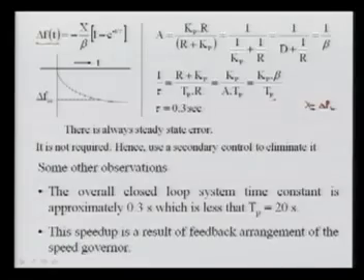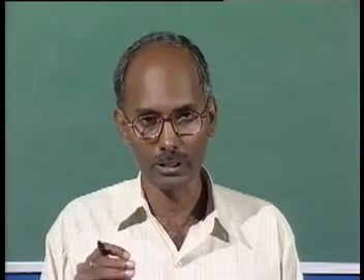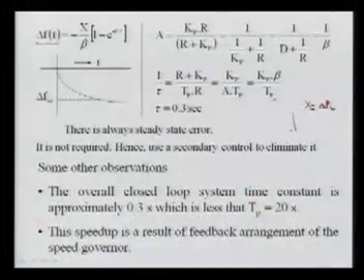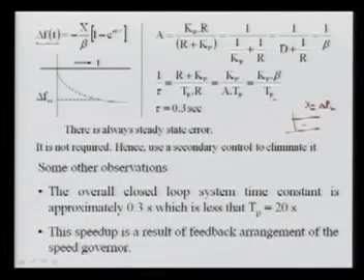It is not a gradual change, it is the step change. If the load is changing gradually, then the load will be met by the governing system as well as the net load release, and the frequency error will not be maximum. But here we have assumed a sudden change in PL, and this is called step response. The negative sign shows that whenever the load is increased, x is positive and the change in frequency will be negative, meaning lower frequency. It is exponential, 1 minus e to the power minus t upon tau, where tau is the time constant.